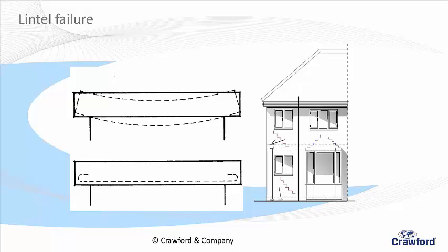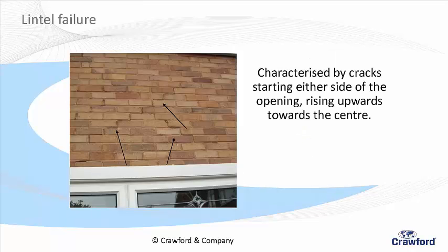Here's a lintel failure in reality. Can you see it? Can you see the cracking on the left and the right? Never quite the same as the textbook, but not bad, is it? There's a step crack there, and there's a step crack just here. The first complaint you'll get on a lintel failure will be a bit of a complaint about the windows just catching and binding. I'm not saying it could be that, but that could be the first sign, okay? That's a little clue.